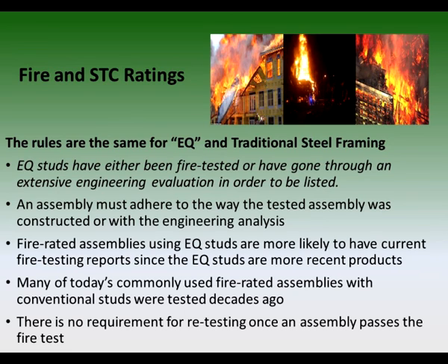One positive about EQ studs is that today's commonly used fire-rated assemblies using conventional studs were tested decades ago, and there isn't a requirement for periodic retesting, despite the fact that some materials have changed over this period of time. Conversely, fire-rated assemblies using EQ studs have been recently fire tested, and the materials represent what is being supplied today.